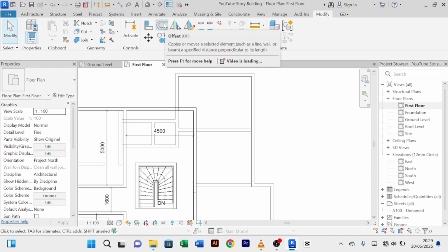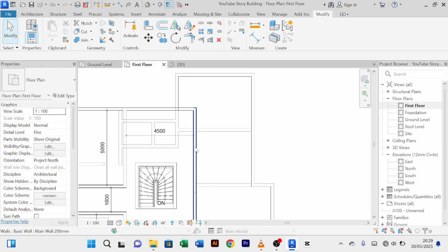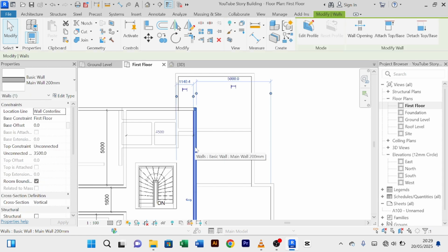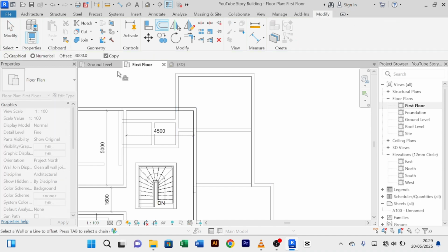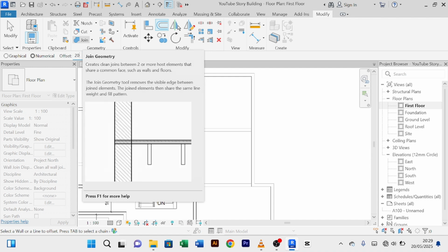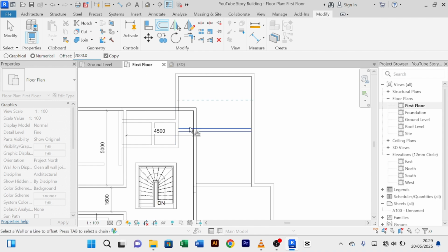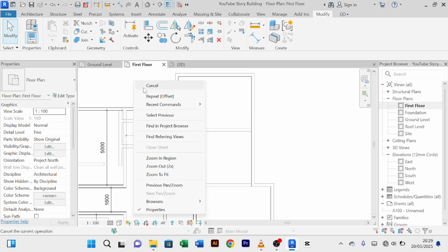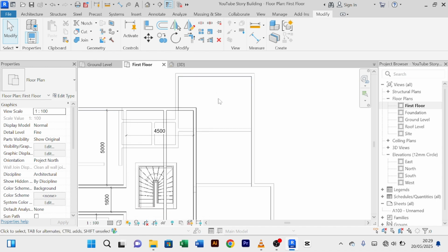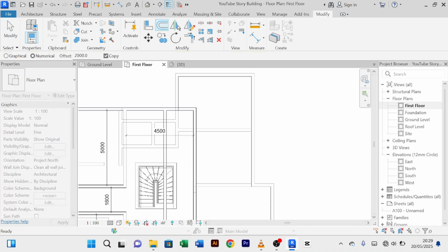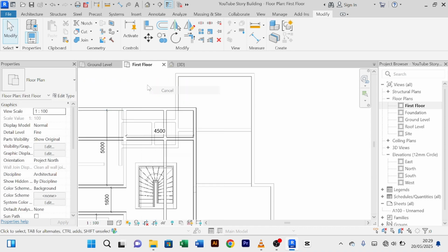So for the washroom, we shall pick this wall, and then we say we offset in, let me say 2 meters, because we want this washroom to have other equipments that people are going to use for bathing and stuffs like that, since it is a gym area. Then we shall offset this wall by, I guess, also 2 meters. 2 by 2, that is a lot, by the way, a lot of